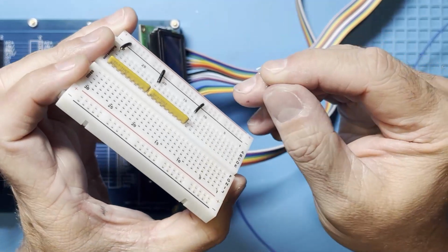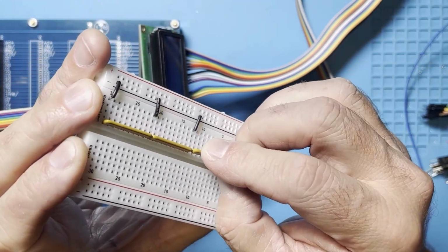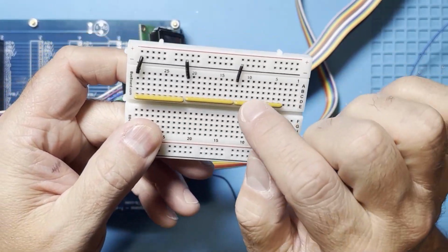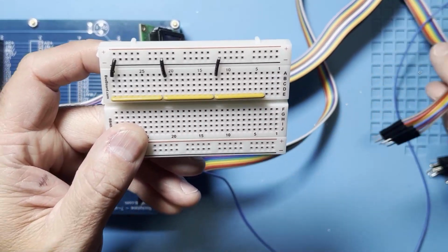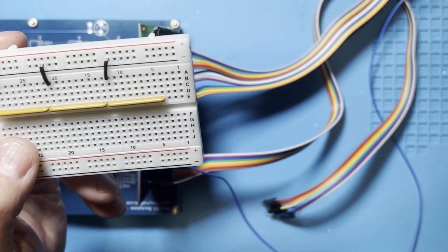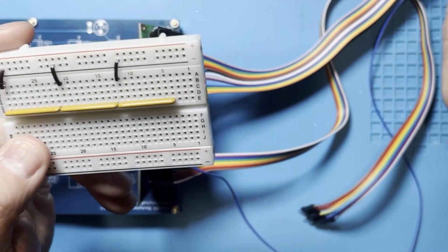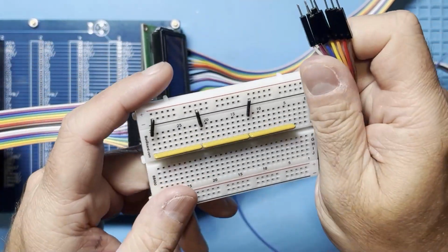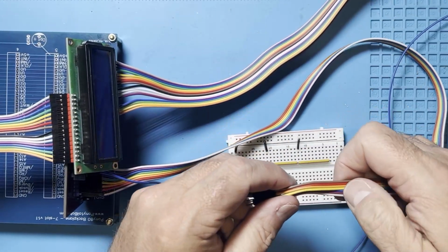And if I plug this in here, just like that, we actually have 3 sets of 8 pins that can be used. So 24 pins, which is the 8 for the data and the 16 for the address. And all I have to do is plug all that in and connect the ground, and we should be good to go. So let me go ahead and do that, and stay tuned. We'll see what happens. I'm really intrigued here.